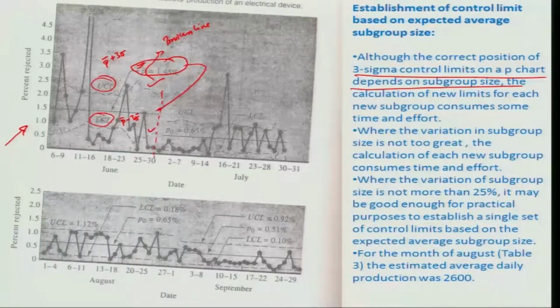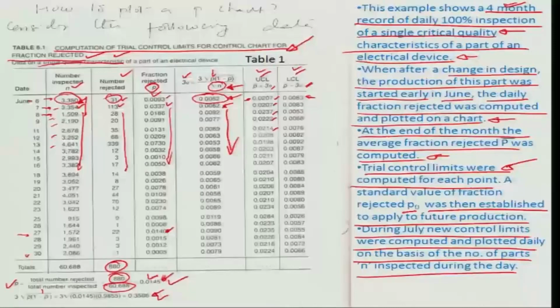Once the limits are defined in the P chart, we start looking at the individual points and see what the outliers are. Here in this particular case, I can say that there are many points. So, these are the individual points. For example, this corresponds to the 7th of June, where there is an outlier, 0.037, and it goes above the upper control limit. Similarly, there may be many such cases from time to time. For example, this again is an outlier.